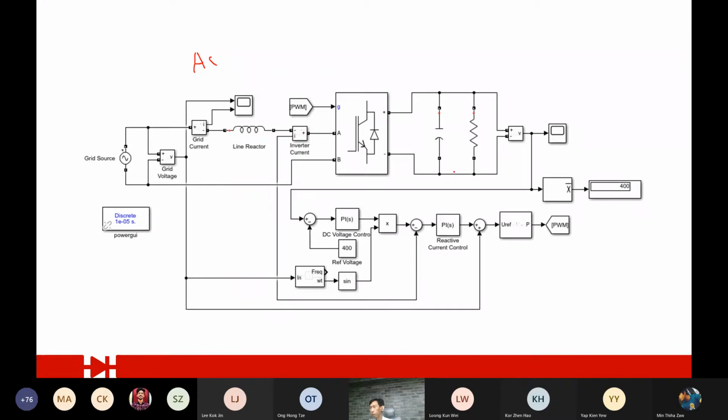All right, so how this control works. Like I said, these are the feedback, the VDC is here. These are the feedback. Again, these are the controls I showed just now. You can control active power, reactive power, and you control the power factor. Similarly, this one also will produce PWM. Remember when we had this DC to AC SPWM? We are controlling with the SPWM.